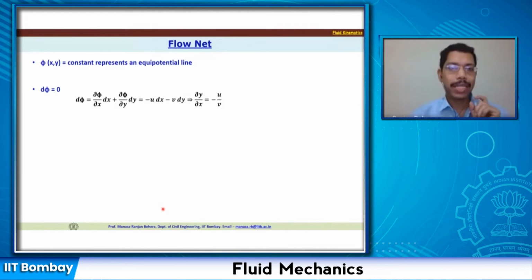And we already know ∂phi/∂x is minus u and ∂phi/∂y is minus v. So I can write down minus u dx minus v dy is equal to 0, which implies ∂y/∂x is equal to minus u by v. All right. So similarly, if I want to write down the psi function and equate it to a constant, that is going to give me the streamline or flow line.